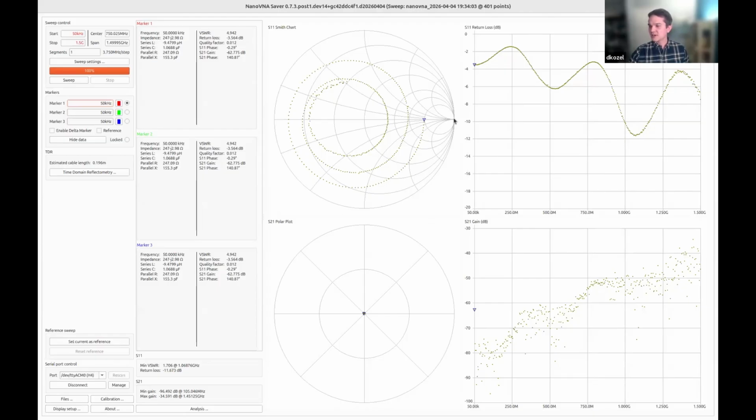Then we get into the Smith chart, which will be a little bit deep to explain if you've never seen it before. But the fun bit is you can approximate the center of the plot, whenever we're going to be seeing it, as 50 ohms. You can actually adjust that. So people working in 75 ohm based systems, for instance, would have 75 ohms at the center of their plot. But every time that we're going to deal with it, pretty much, it'll be 50 ohms at the center. As you move outwards along the center line, you're changing just the resistance.